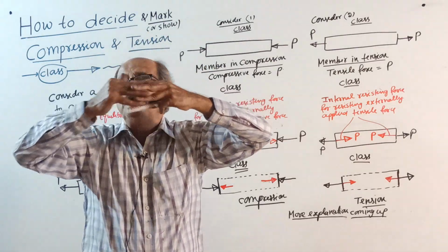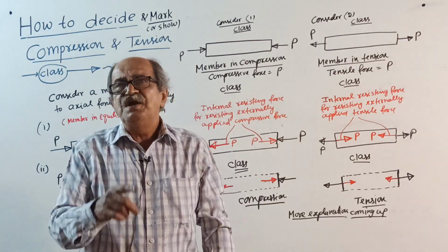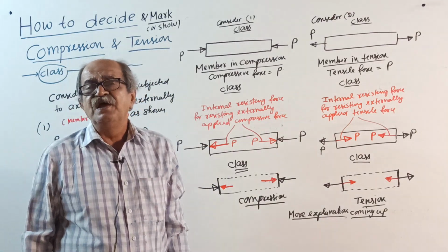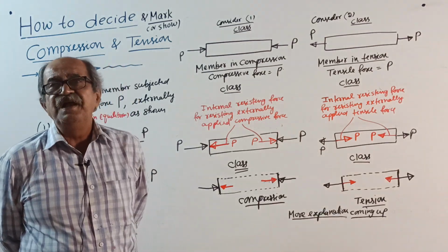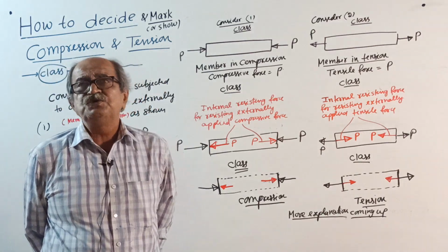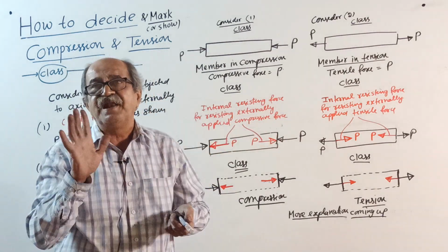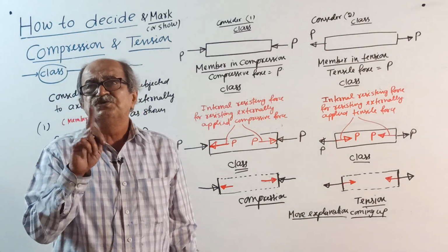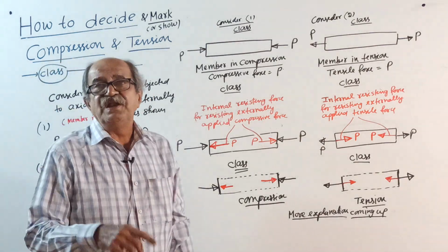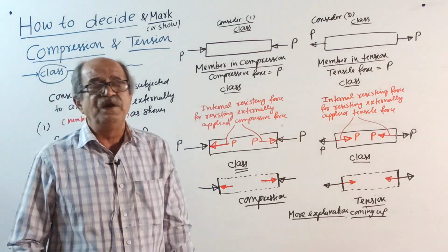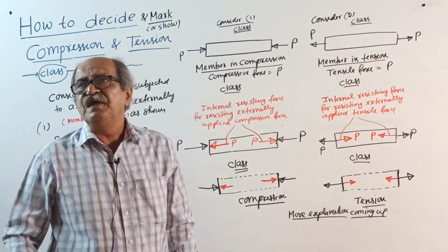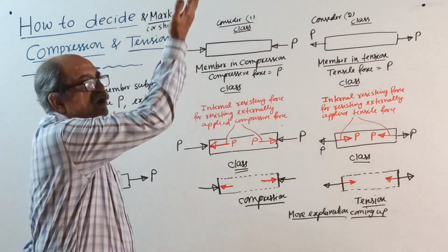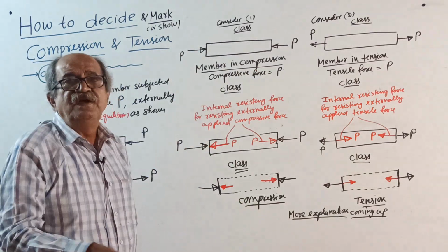P, inward acting. I will tell in the class, when you tell compression and tension or bending moment later, do not use direction like right side, left side. When you define a force, you tell right side, left side, positive, etc. Correct. But when you want to talk about compression or tension, do not use direction. Use nature. And one more thing I will tell in the class. When you want to explain external forces or equilibrium, right side, left side, upward, downward, clockwise, anti-clockwise, direction based.